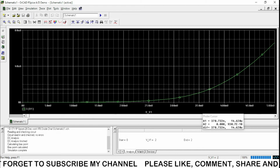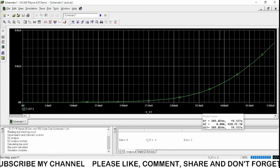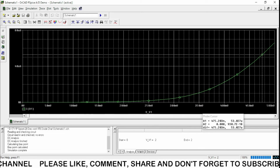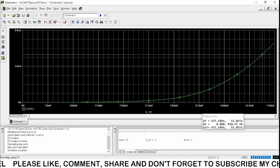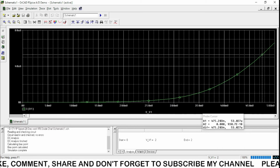So from that you can calculate the dynamic resistance value R. Now we have to go to another point, suppose this point, we can say this point is B. So we have 475 millivolt as the voltage at that point, and 53 microampere as the current at that point.